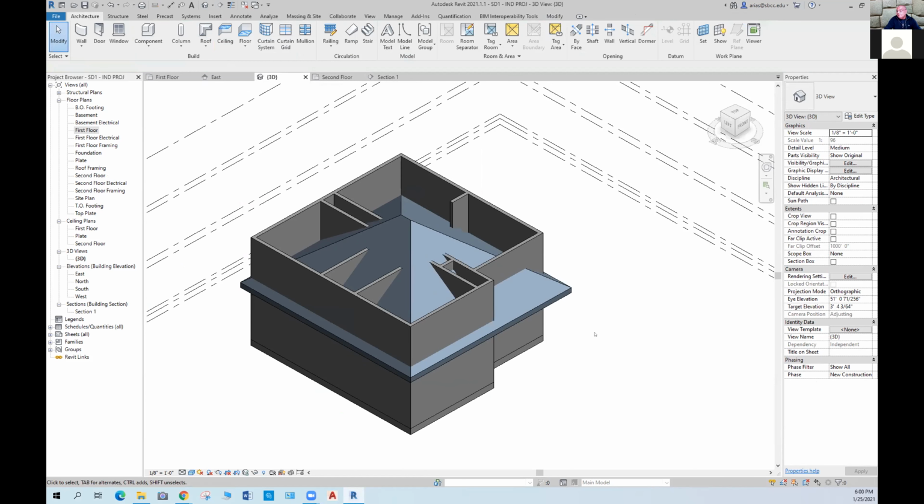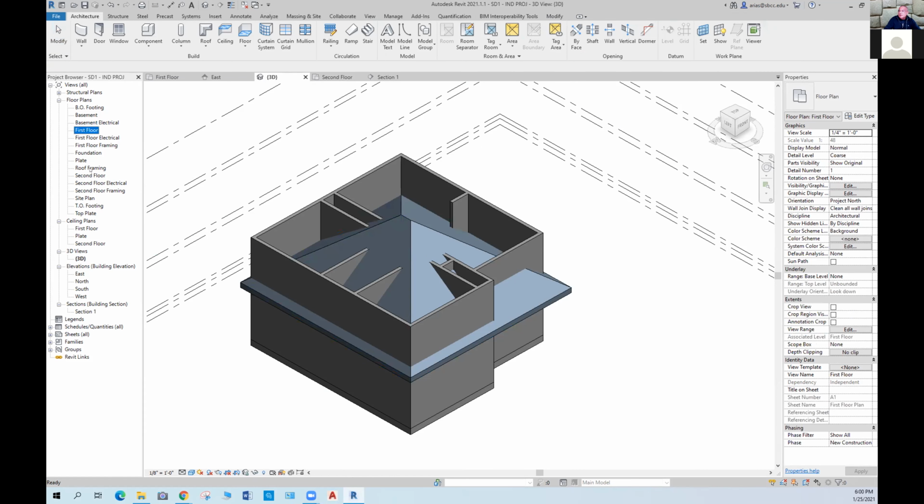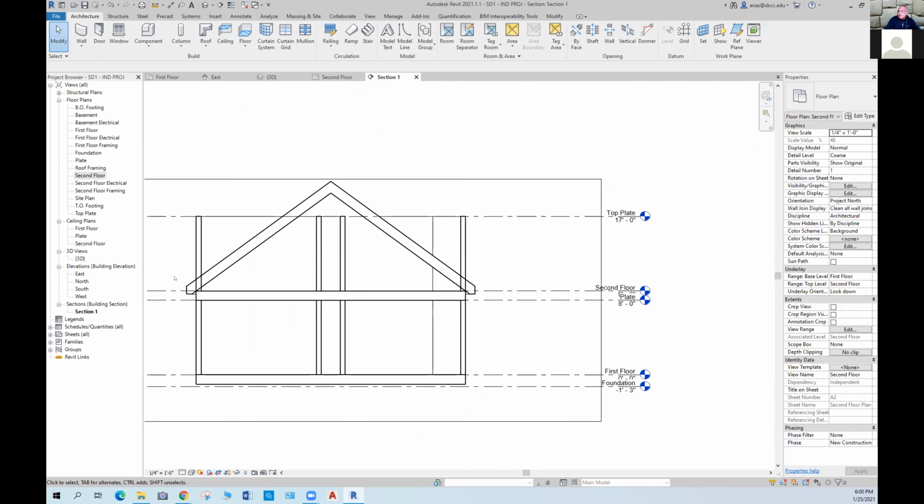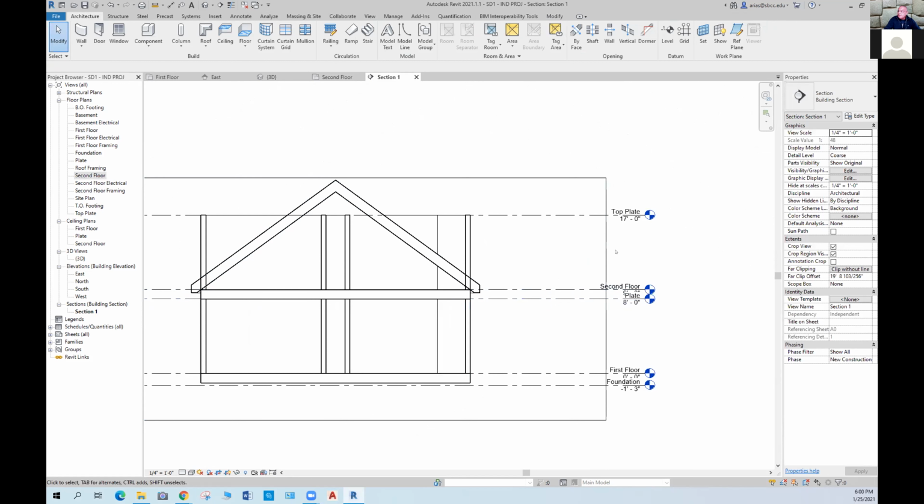And you see what happens there is that I started the roof on the second floor level. So I shouldn't have done that. I should have started the roof on the level that it needs to be. And so that's why I created this section, because I want to make sure I know which level I need to create the roof from, and the roof needs to be created from this level. So let's delete this roof and do it again, this time from this level.